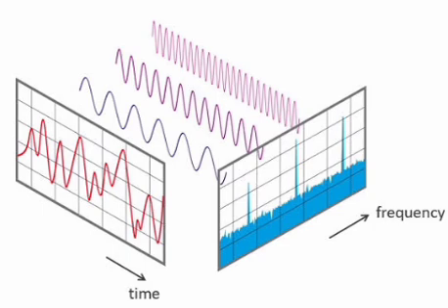Miscellaneous: unit doublet function. The derivative of a unit impulse function is called the unit doublet. Properties: del dash of t equal to d del of t by dt. Del dash of at equal to 1 by modulus of a, del dash of t. All even derivatives of del of t are even functions of time, while odd derivatives are odd functions. If f of t is any function, then f of t del dash of t minus a equal to f of a del dash of t minus a minus f dash of a del of t minus a. Integration from minus infinity to infinity of f of t del dash of t minus a equal to minus d by dt of f of t at t equal to a.